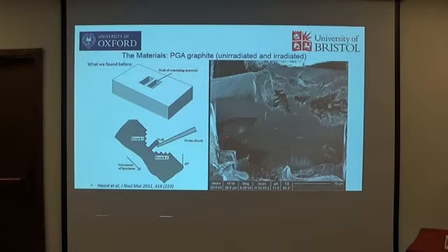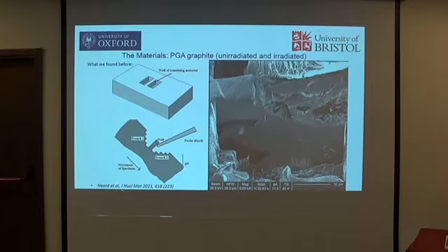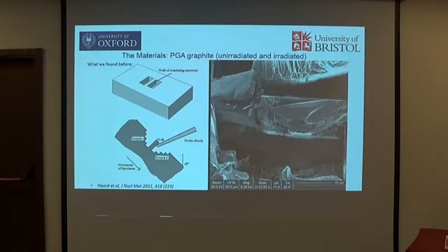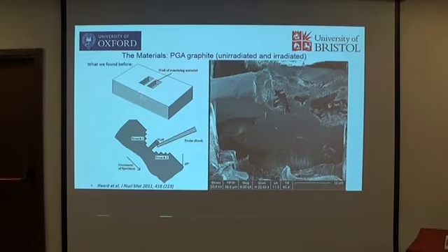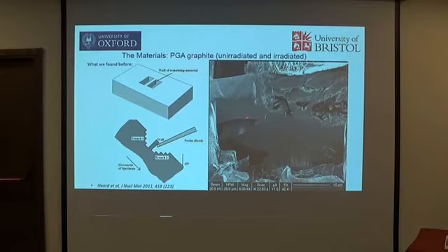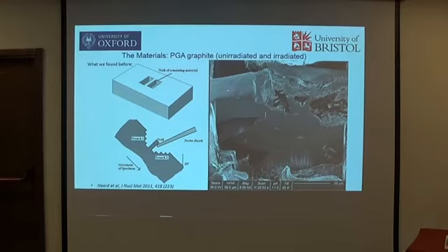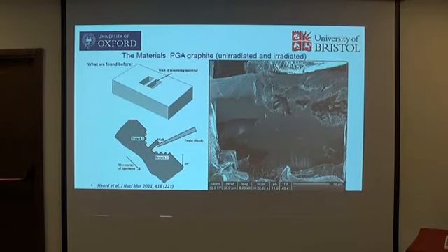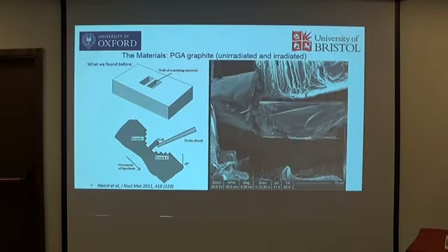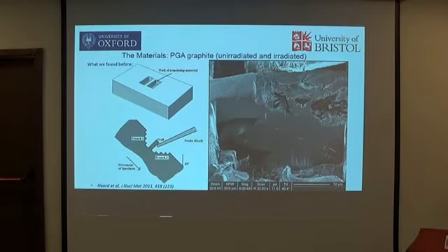We're trying to understand what irradiation does to the matrix material. This is previous work published by Hardie et al. It's again in a FIB. We made a wall in the middle, and then the sample was moved towards a probe. You can see the deformation created on the wall. We think there's twinning happening after irradiation, but this was not observed in what we call virgin graphite. It doesn't exist there. So that means neutron irradiation has created some sort of damage and a change to the material property.